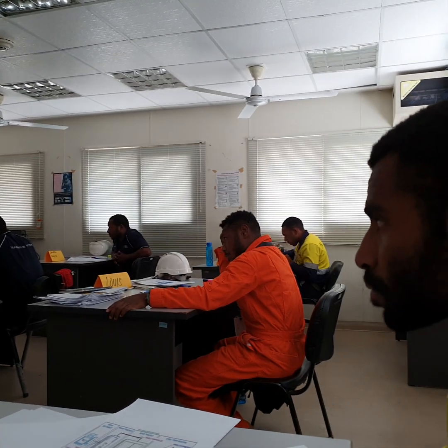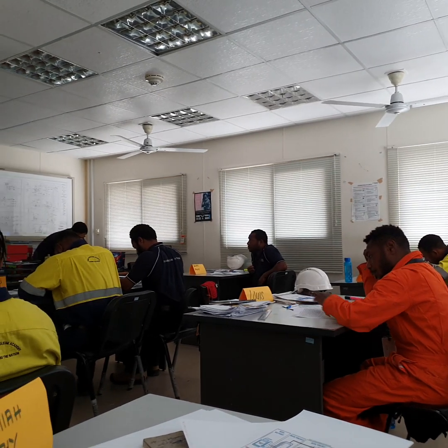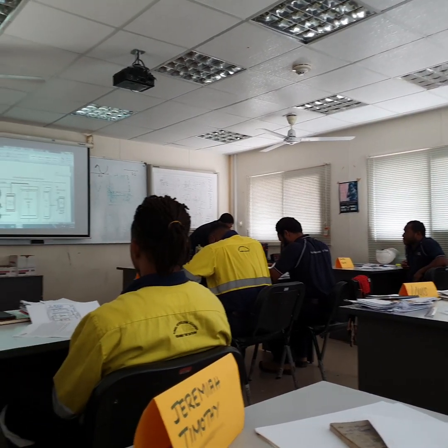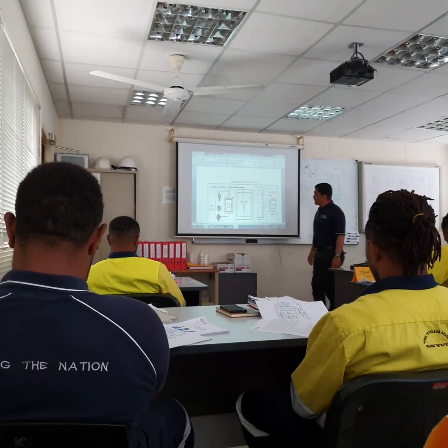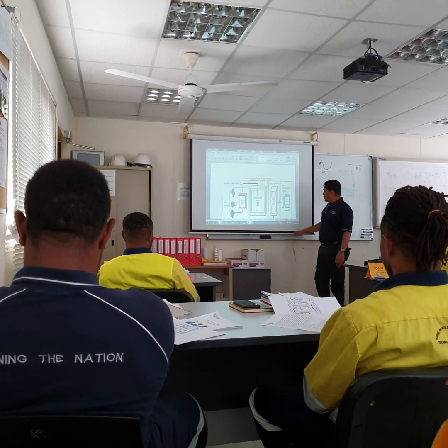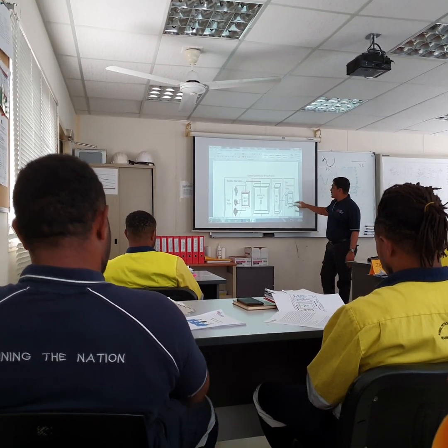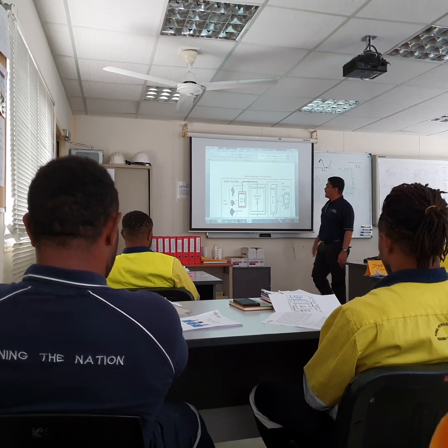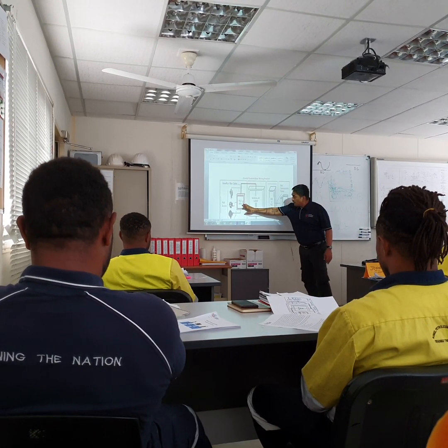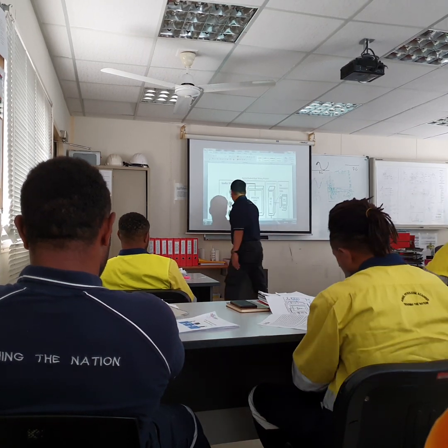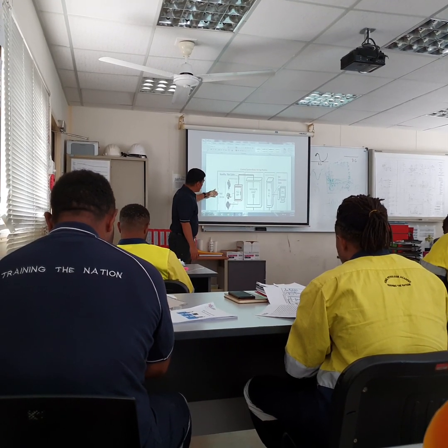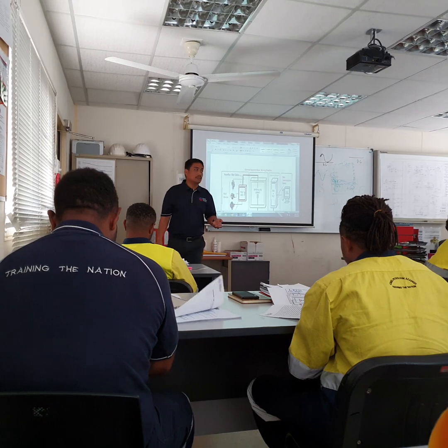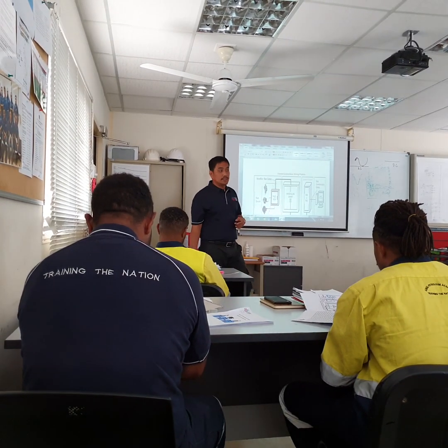So as you can see on the diagram, this is your control system basic wiring practice. You can see a marshalling cabinet. You will find the computer, data communication cables, DCS or PLC, marshalling cabinet, field racks, field box. On the field box, the field devices are connected. What are the samples of those field devices? You studied that with Nathan in instrumentation.